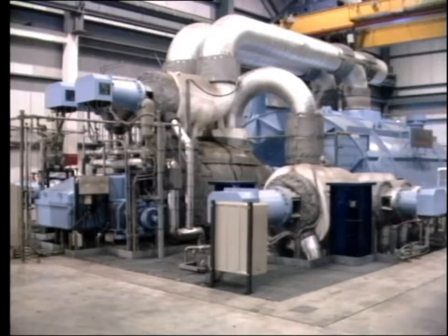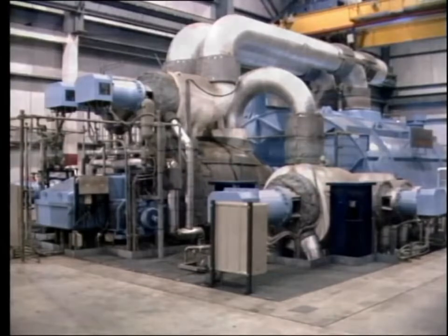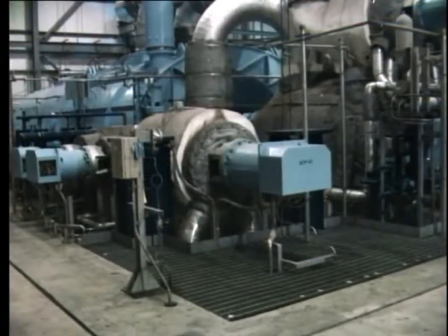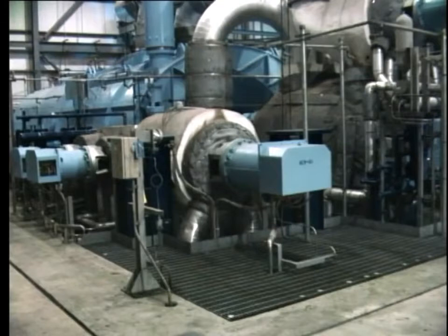In large machines, say greater than 100 megawatts, it is more common to have 2 steam chests, one above and one below the shell, or located one on either side of the turbine. In this case, multiple control valves are located in each steam chest, with steam lines connecting to the turbine shell at the high pressure end.